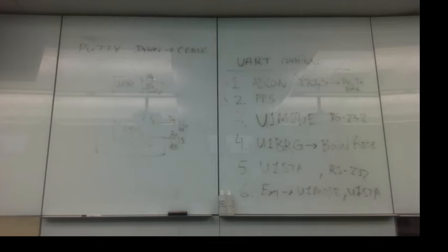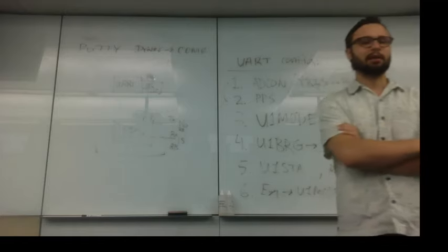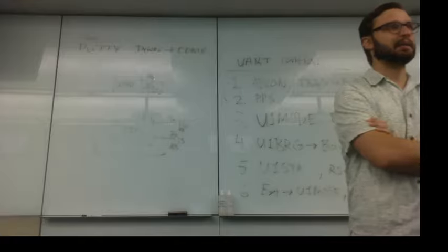The interrupt flag, on the other hand, will be set when you actually send the data. So the interrupt flag is more useful. The interrupt flags are useful in general, whether or not you're using interrupts. They're kind of the thing that tells you whether or not the data has been sent or received.